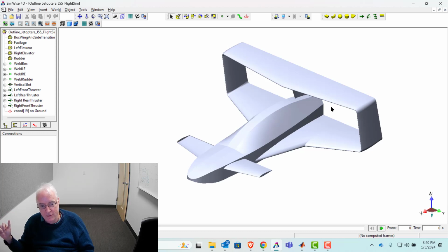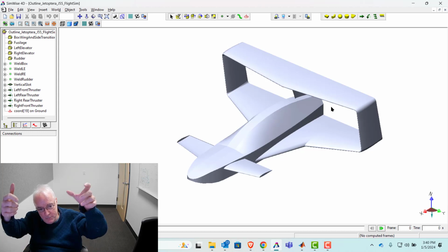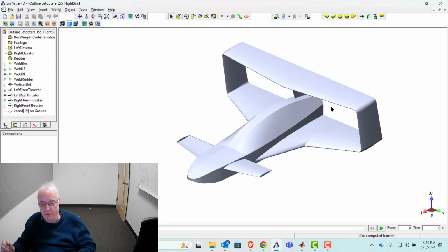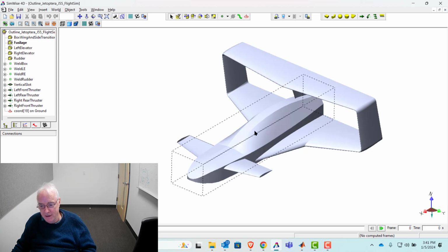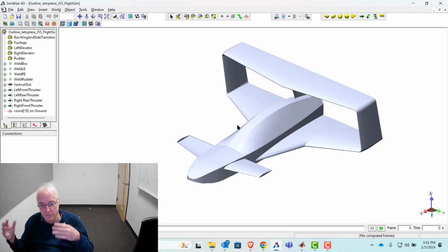They need to be calculated, so not only do they add up to the lift forces that we need, but they also sum to a 0 moment. One way of thinking of it is to take the moments with regard to the center of mass, through which the gravitational force acts, and make sure those moments add up to 0. Flight controls do that for vehicles like this.